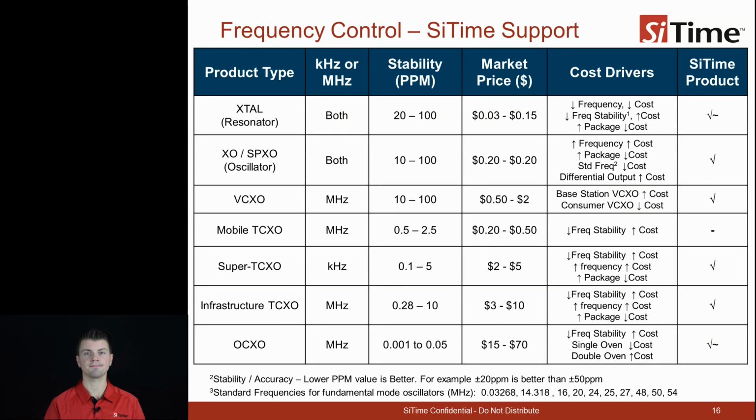When you look at stability, the higher stability devices usually cost more because they have additional temperature compensation circuitry, and also because very high stability devices have to be calibrated across more than one temperature. Such testing requires a temperature change and requires time to ramp the temperature to different points. This extra processing time costs money.